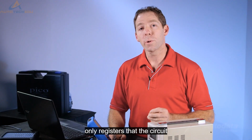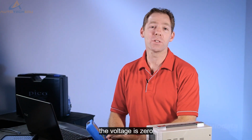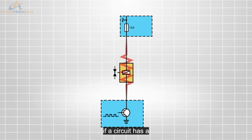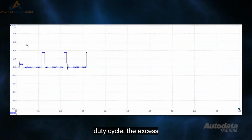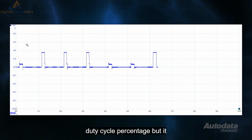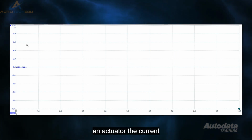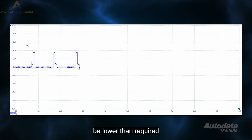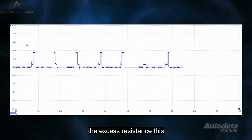The meter only registers that the circuit has been pulled from ground to voltage. In reality, this is when the circuit is turned off. The on time is actually when the voltage is 0. If a circuit has a resistance fault, it may not be detected using a multimeter set on duty cycle. The excess resistance will not affect the duty cycle percentage, but it will affect the operation of an actuator. The current flow in the circuit will be lower than required. This is due to the reduced voltage caused by the excess resistance.